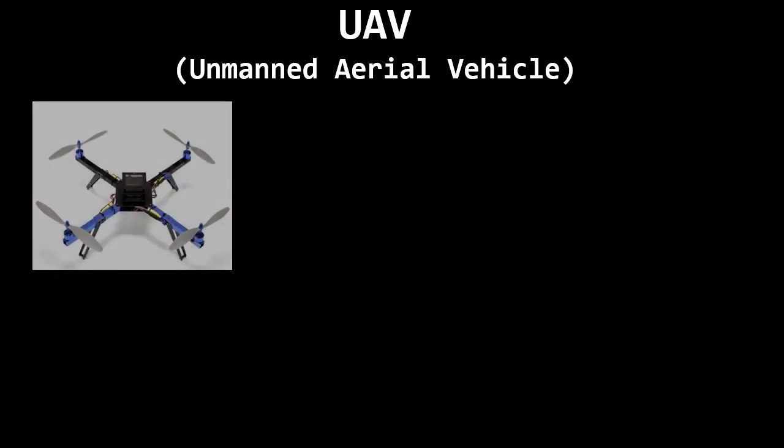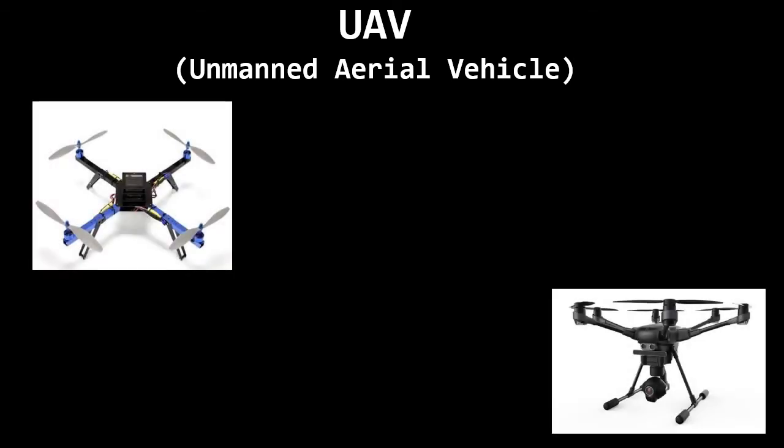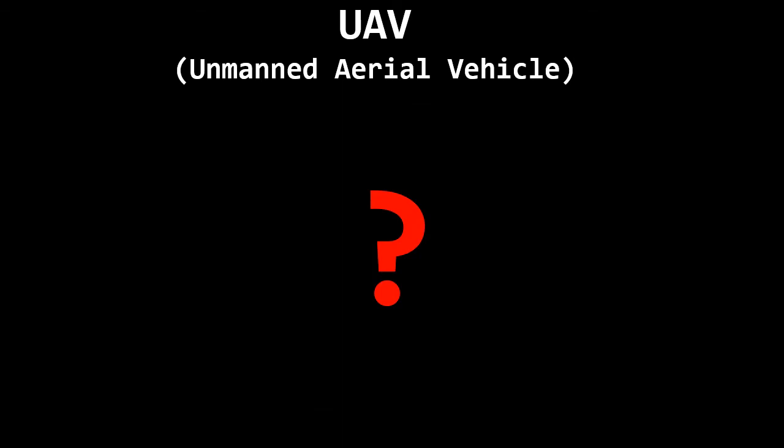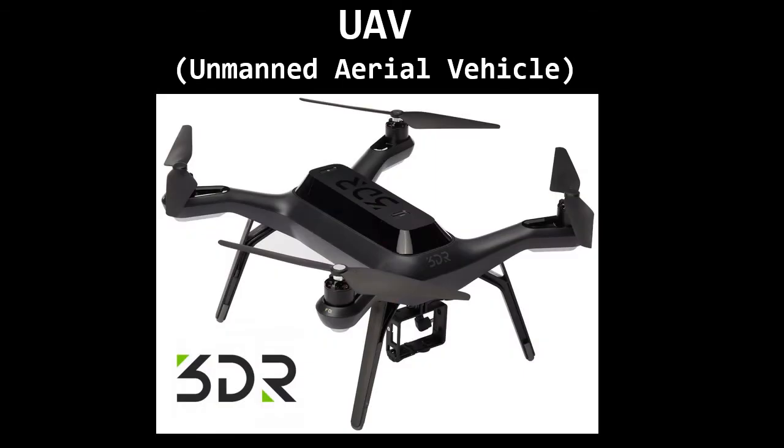The central component of the system is a UAV, or unmanned aerial vehicle, or, as it is known to the commercial public, a drone. The most challenging part of this project was locating an open-source, ready-to-fly unit, which could be integrated with the computer vision and infrared camera inputs. In the end, we decided on a 3DR Solo, possibly the most inexpensive, open-source quadcopter on the market at the moment. The Solo, with dual onboard computers that run Linux, is a smart drone that can be reprogrammed with Python and integrates with the ground station computer vision code previously mentioned.